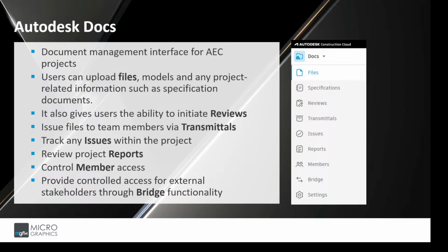The holding area serves as a crucial element of the Autodesk Docs system. If a file is uploaded with a name that does not conform to the project standard, it is placed in a holding area where it must be corrected before becoming visible to the rest of the team.